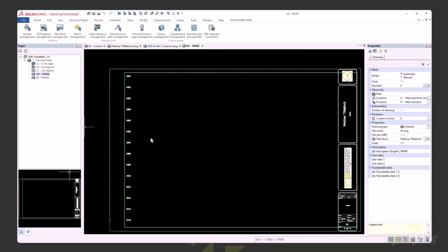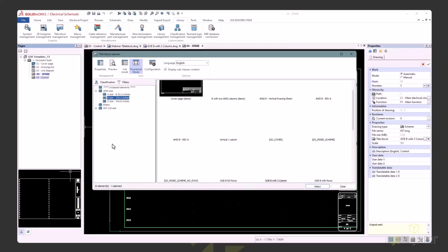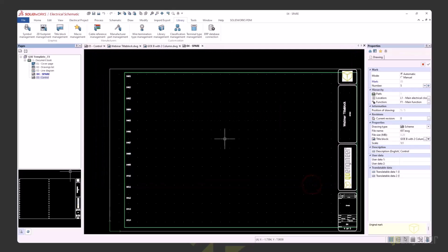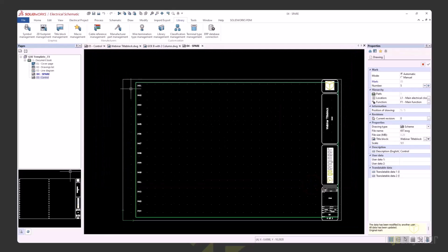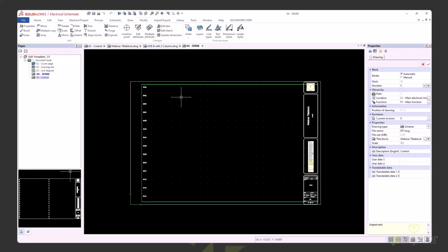Now, if you want to test it further on another page, simply replace it on that secondary page. So you can say replace, find that title block. I like to use the filters tab because it's a little bit faster. Say any class, and there it is. Okay, you can get rid of these outside lines. You can start scaling. Remember that you have modify and scale, offsets, stretches. You can mirror things. This will give you some nice control.